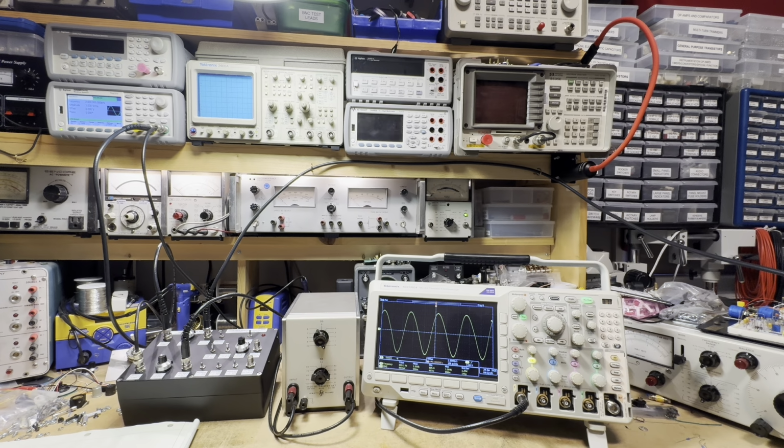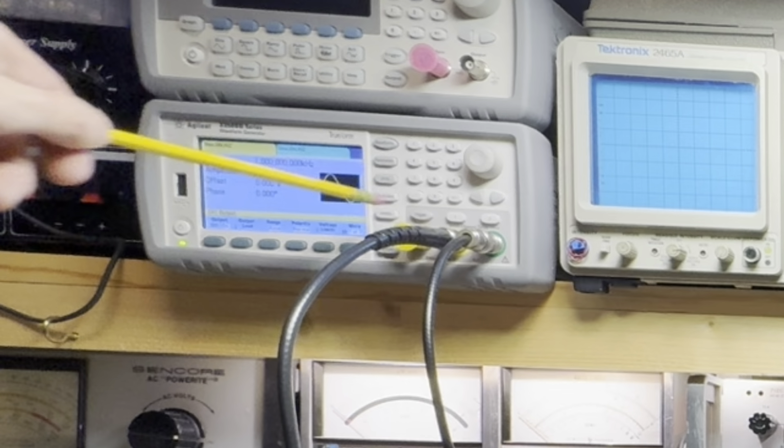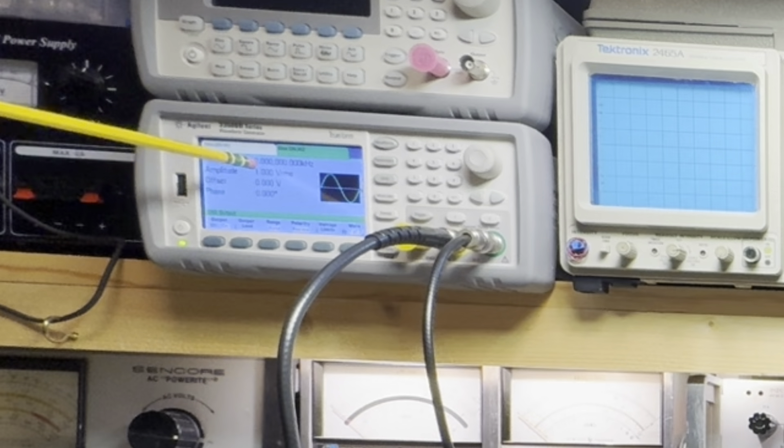All right, let's have a look at our setup here. Now, we've got some fan noise, so I've got the spectrum analyzer turned on, but we'll just have to deal with that. All right, so let's talk about our setup. What we've got is our function generator coming in here. This is producing two signals. I've got a signal on channel 1 at 1 kilohertz, and I've got a signal on channel 2 at 2 kilohertz. Both of these signals are at 1 volt RMS.